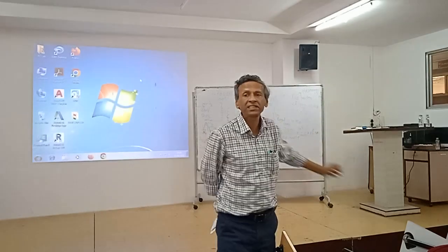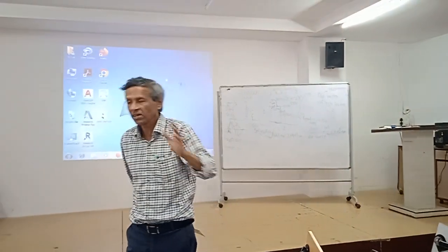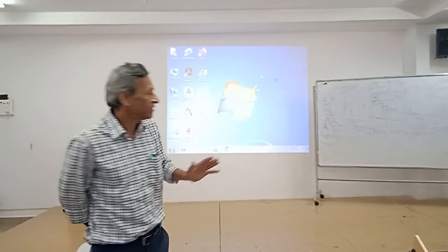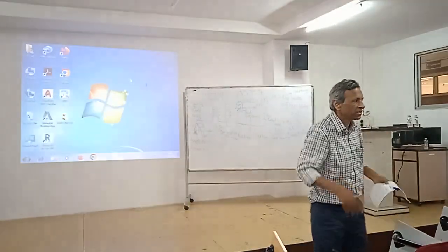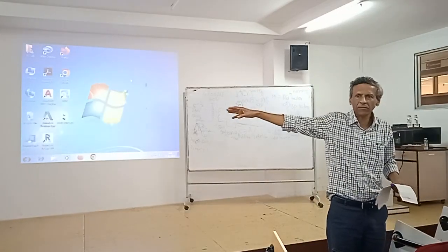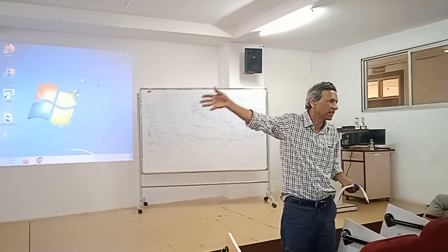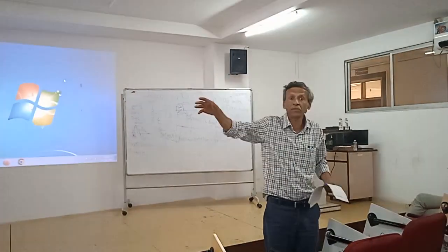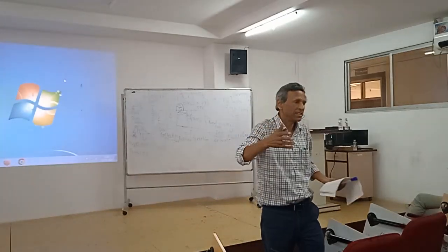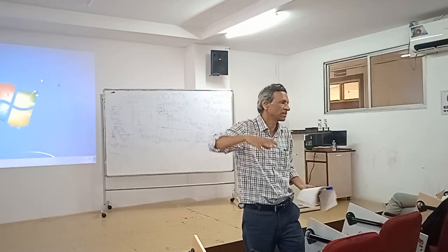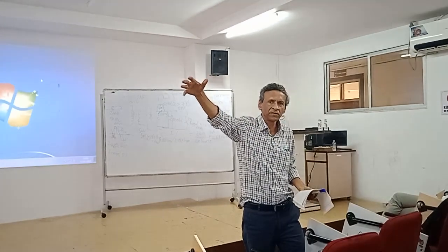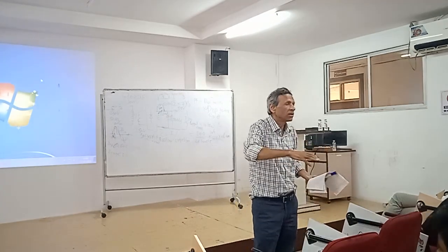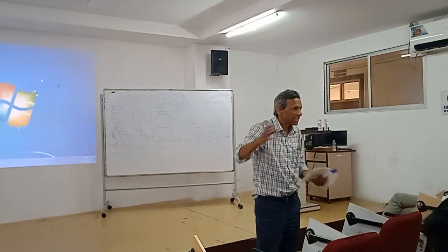So this rectifier is the biggest culprit. It is generating so many harmonics, and at the same time, up to a certain extent based on the load, lagging power. And that's why the meter will register reactive power, not harmonics. A normal meter may not have that sophistication to go for FFT and give you the information of harmonic current or THD, because these are all advanced power analyzers. You might have heard the word power analyzer. These are expensive. But ultimately harmonic is also a reactive power.